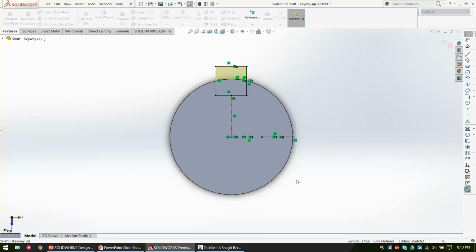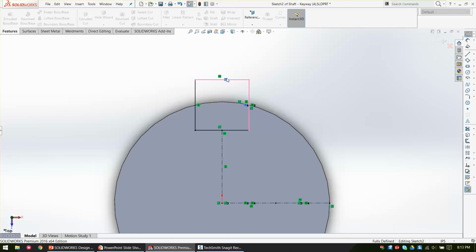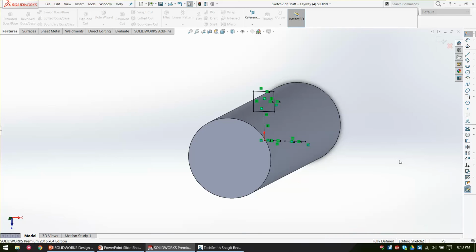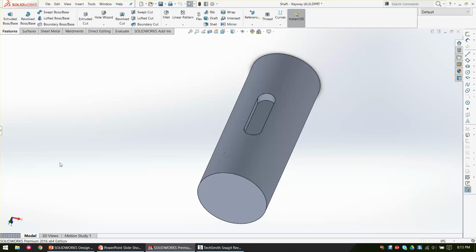I don't care what the diameter of the shaft is. I don't even have to commit to memory what keyway we use in shafts from an 1/8 inch up to, I think the Machinery's Handbook goes to 10 inches or something. Then you get some odd different variance because it's removing too much material. But I don't even have to remember what all that is. Then I just draw a single vertical line to get my slot centered, have a rectangle with both sides equal, with midpoint coincident to the edge of my shaft, and cut extrude to my desired length